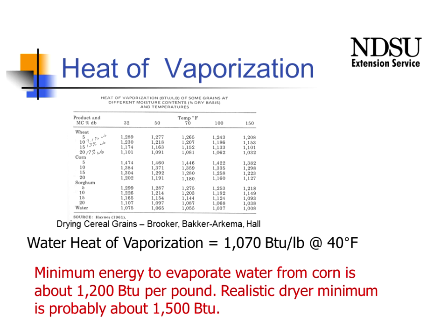If we were just vaporizing water, we're looking at roughly 1,100 BTUs required to evaporate a pound of water. If we look at corn, we're probably somewhere in the neighborhood of about 1,200 BTUs as being 100% energy efficient as far as the energy required to evaporate a pound of water. From a grain drying standpoint, I think a realistic expectation might be something in the neighborhood of 1,500 BTUs as being about as good as we could expect to obtain.